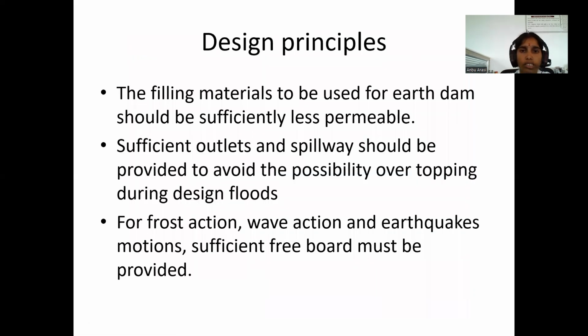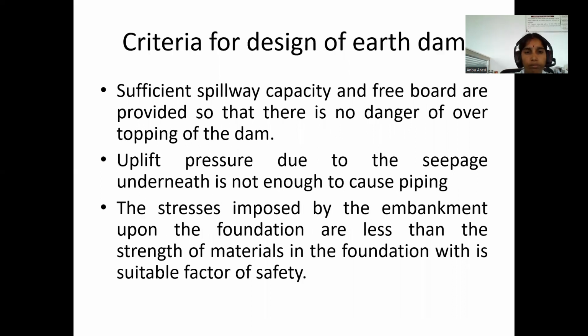Design principles. The filling materials to be used for an earth dam should be sufficiently less permeable. Sufficient outlets and spillway should be provided to avoid the possibility of overtopping during design floods. For frost action, wave action, and earthquake motion, sufficient freeboard must be provided.